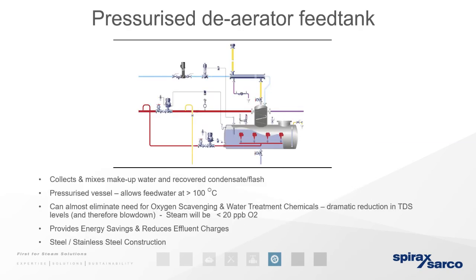More advanced boiler houses are now keeping their feed water under pressure of around 0.5 bar, which gives you approximately 105 degrees Celsius. The benefit this brings is, first and foremost, that it is pressurized, so there is no venting, which means that flash steam losses can be absolutely reduced. A higher temperature equals a more responsive boiler whenever there is a sudden demand, as I've just explained. And also, higher temperature equals less energy consumed to raise steam.